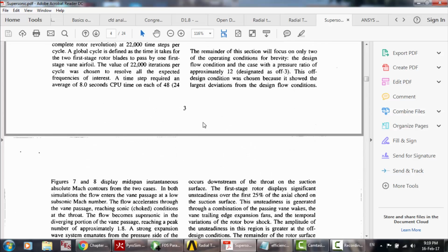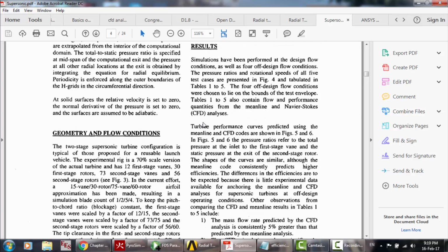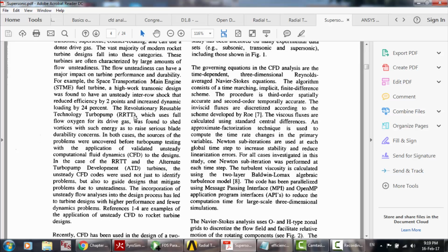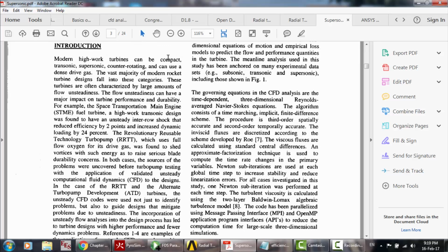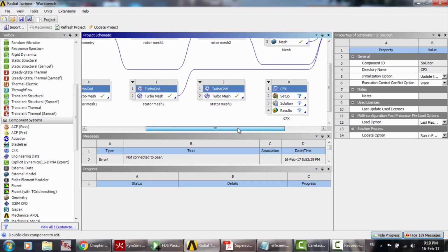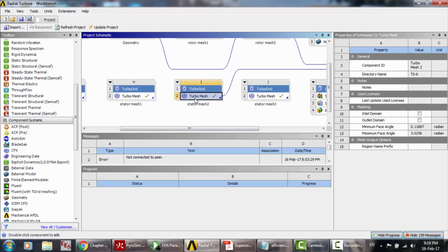Because you have to get the required y plus, and then you can carry out many mesh sizes, and then you can transfer the mesh into CFX. So you have here 3 mesh sizes. Let's take a look at this.